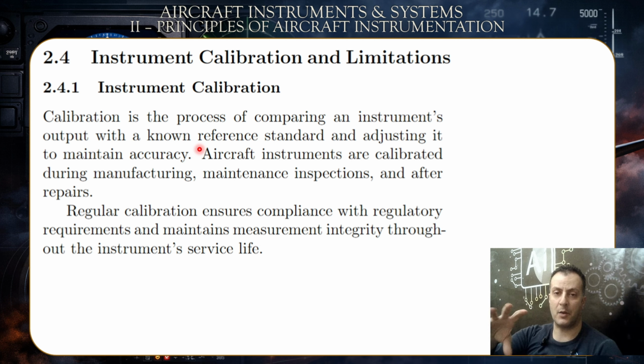This is how the diaphragm within the altimeter would be expanding in reference to the external air, which of course will have its own pressure decreasing as the aircraft climbs. But as this external pressure decreases, due to the difference between the static air on the ground and this external ambient air, you would have a correct reading of the current altitude. This is why we calibrate the altimeter on the ground.